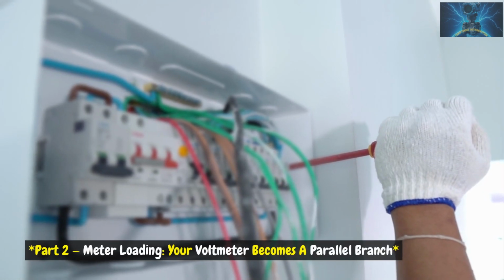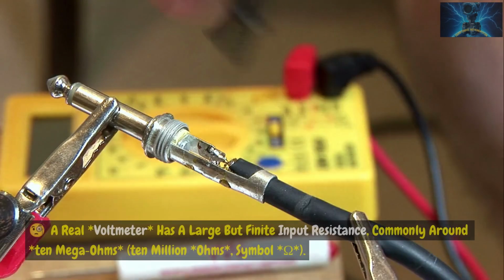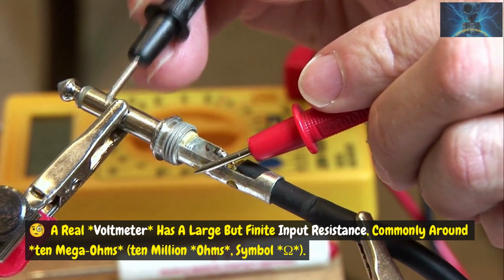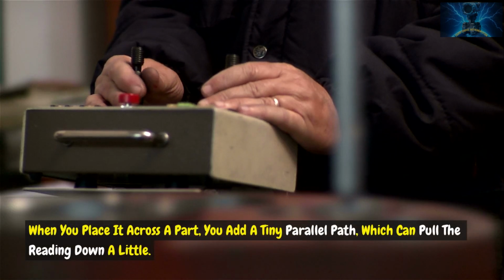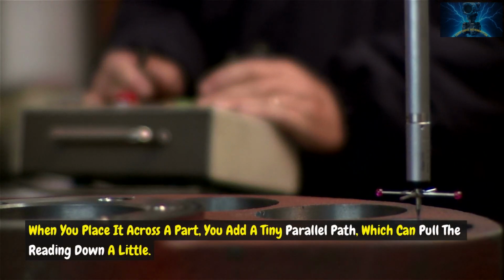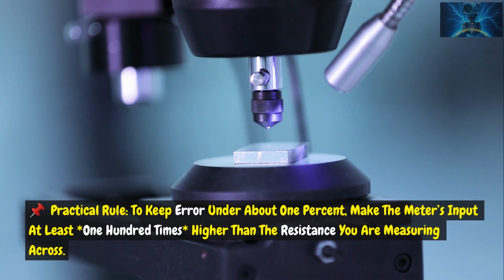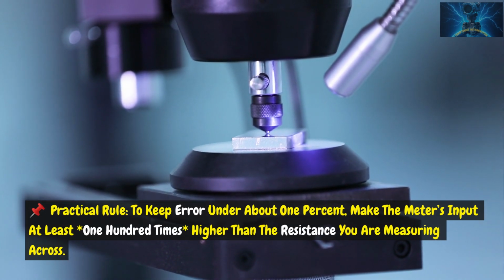Part 2. Meter loading. Your voltmeter becomes a parallel branch. A real voltmeter has a large but finite input resistance, commonly around 10 megaohms, 10 million ohms, symbol Ω. When you place it across a part, you add a tiny parallel path, which can pull the reading down a little. Practical rule: to keep error under about 1%, make the meter's input at least 100 times higher than the resistance you are measuring across.